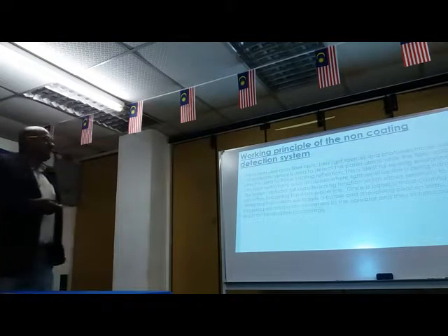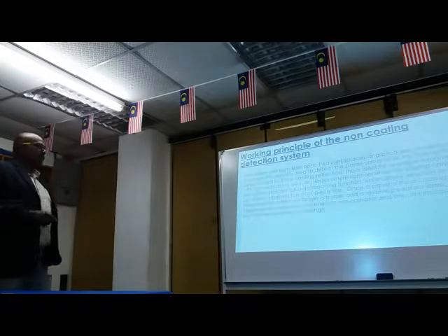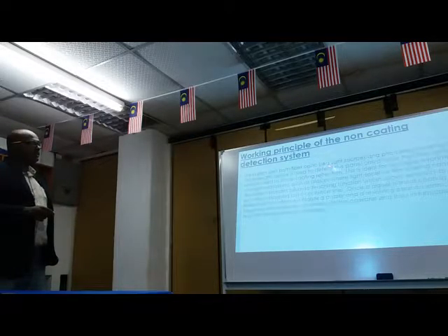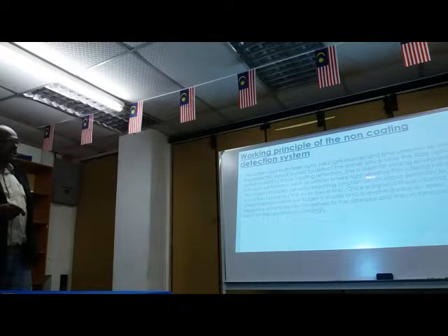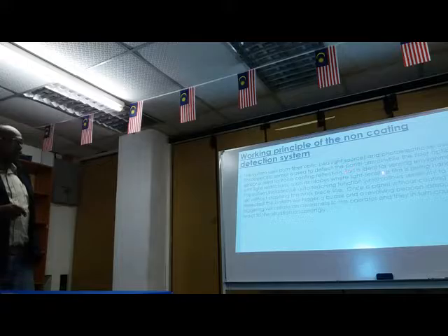So, the working principle of the non-coating detection system. The system uses both a fiber optic red light source and a photoelectric sensor. The photoelectric sensor is used to detect the panel arrival, while the fiber optic sensor is used to trace coating reflection. This is ideal for sensing environments with light restrictions, such as our place where the light-sensitive film is being handled. We have a yellow light, and this is the best solution for it.